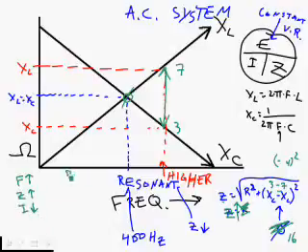Well, you probably don't remember this formula, but power equals amps times volts. Watts equals I times E. Well, E is constant. Voltage is held constant by our voltage regulator. If current flow goes down and voltage is constant, then power is going to go down. Wow, watts or power is going to go down. If power goes down, then two things are going to occur.